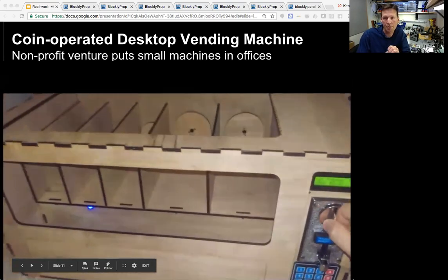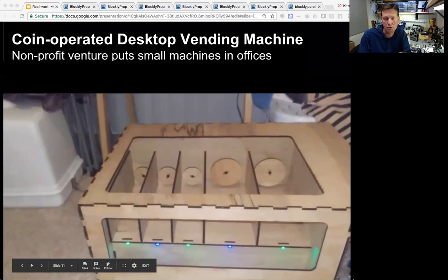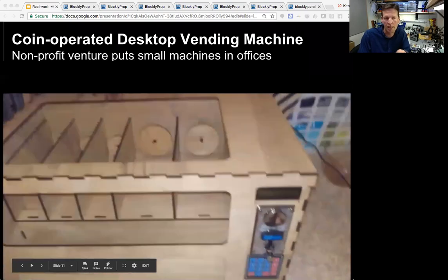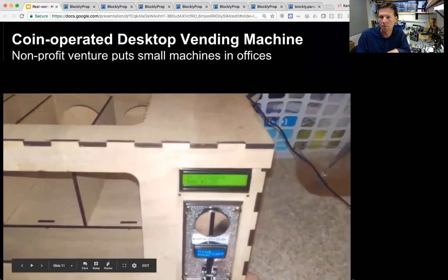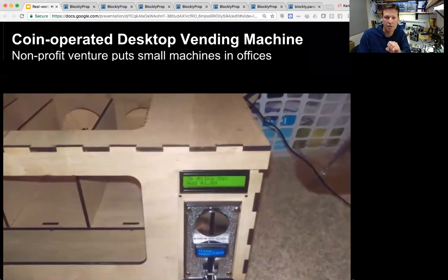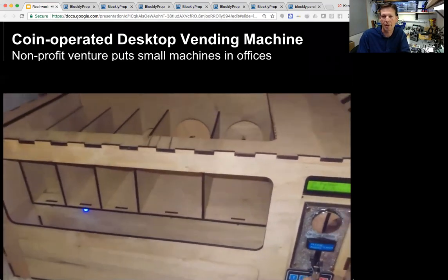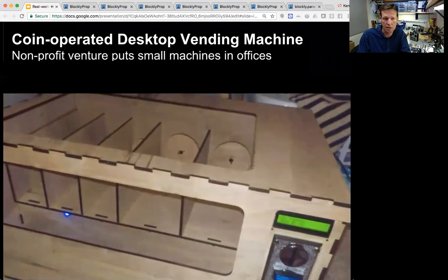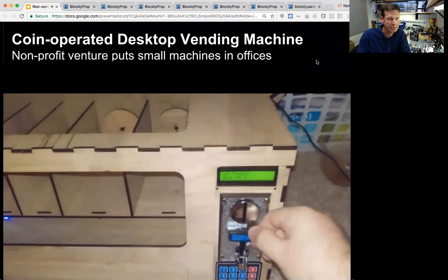So this involves setting a pin, which turns on a motor, and that's done on a separate processor because these motors, which are DC gear motors, will have a little auger or screw. They will drive until the candy is dispensed, which is detected by an optical sensor. So we want to get that right so that somebody doesn't get double the candy. So there's an input pin that waits for the motor's end stop to be reached. Once the candy is dispensed, everything is turned off and reset. The money total goes back to 0. Okay, so you could sell more candy. Interesting project?